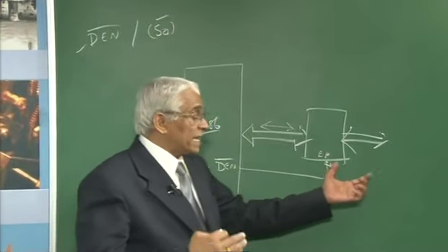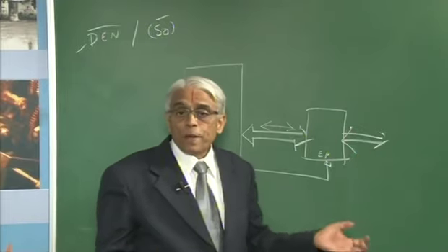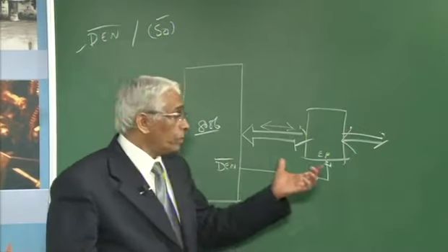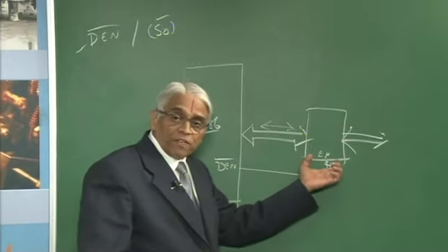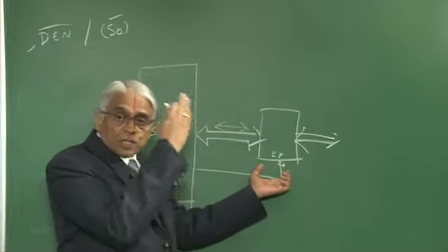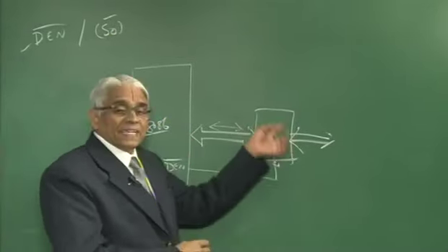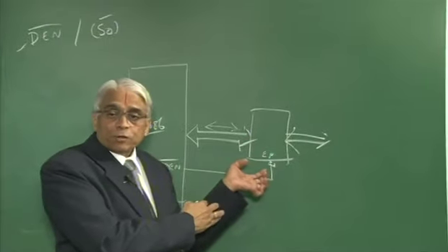Whenever it is connected to the external power supply, if there is any short, there may be a problem to the microprocessor. When you use a buffer, this buffering device can stop the signal from damaging the microprocessor; the buffer gets damaged instead, which is much cheaper and can be replaced.